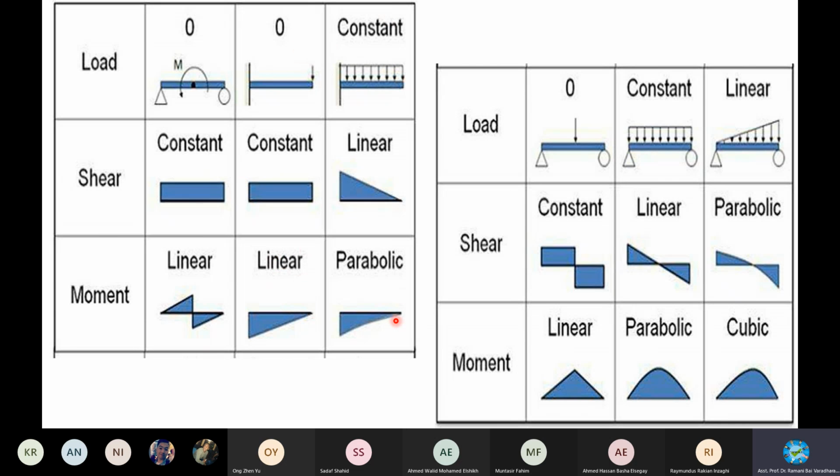And then the UDL, start from here. Again, because it's a fixed end, you will have a fixed end moment, the resistive moment will be there. Thus you have some value, which is a hogging type. Both cantilevers are hogging type. That's why it's negative at the bottom. You can follow either positive or negative, it depends on your convention.